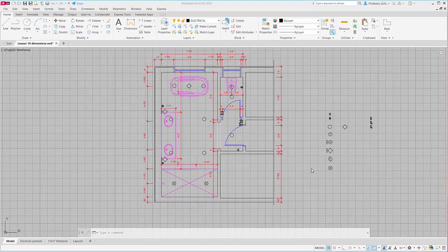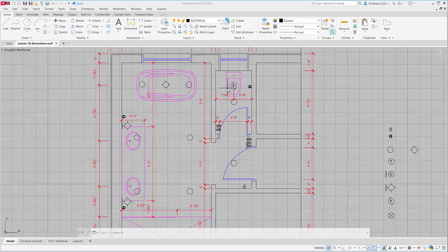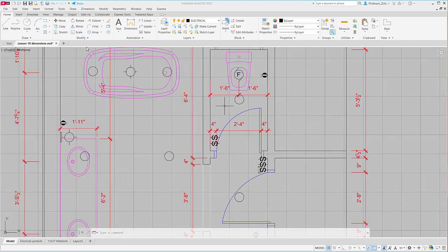I've gone ahead and completed the drawing, inserting all the different electrical symbols that we have for this project. And now we have to identify how the switches are attached to all the different units here. So we have fans and suspended lights and pot lights and so on. So the easiest way to do this is to use splines. I'm still in the electrical layer.